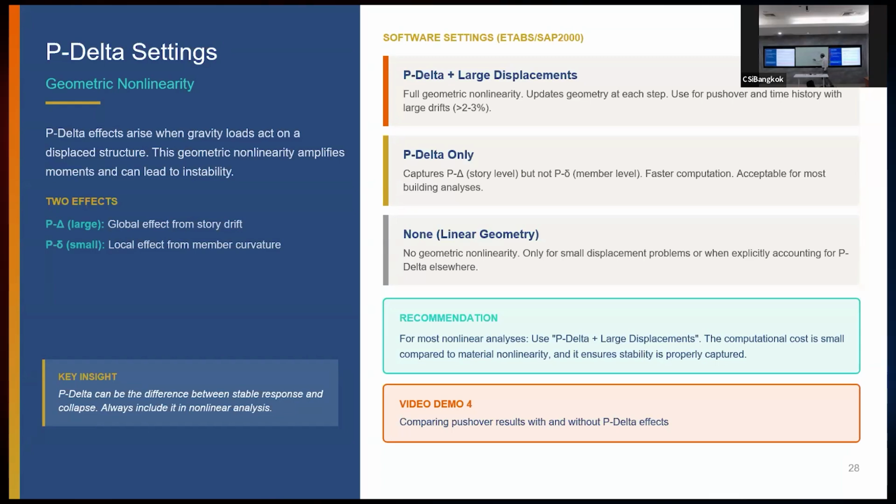And then after the deflection is increasing, it will become a flat beam with a hinge. Of course, a flat beam with a hinge has no stiffness, right? Because it's a hinge. So it will suddenly drop to zero stiffness. And then again from here, in the other direction, it can still carry the load in tension.